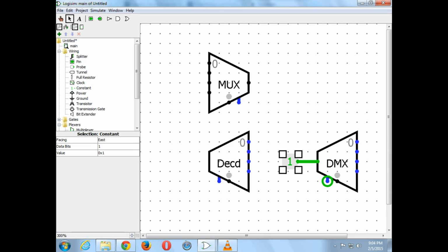Is that okay? That's the explanation of a decoder, which is a special case of a demux. And the way you remember a mux versus a demux is they're just reversed of each other. One has multiple inputs and 1 single output. The other one has 1 single input and multiple outputs. That's all. And the mechanism allows you to switch which input to connect to the output, or which output to connect to the input. And you can also disengage and say, okay, let's not drive the output at all.